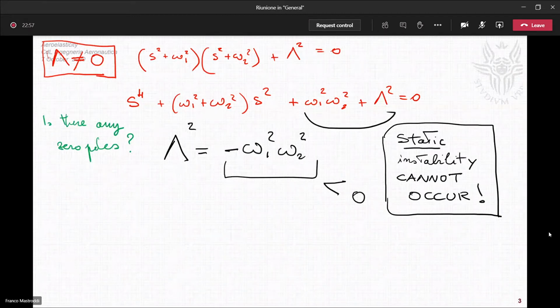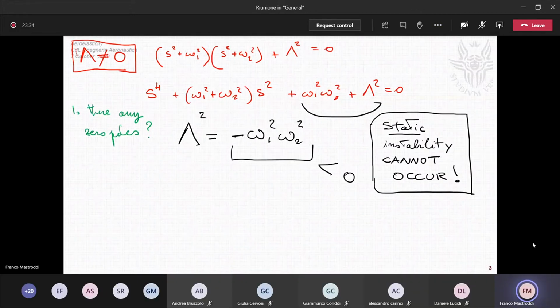And this is interesting because this is the base concept of a flapping flag. When you see a flag, a flat surface, very flexible, like a flag or like a membrane, and you have a wind, you probably don't have just a static stability. You should have almost always oscillation. Okay? And this is an important result we have found. And now we want to study this kind of instability in depth.